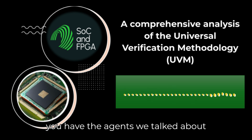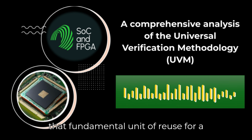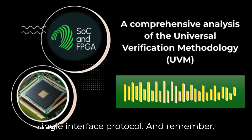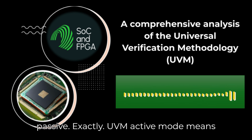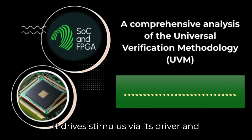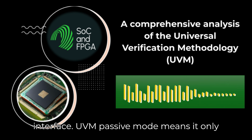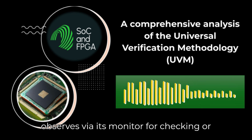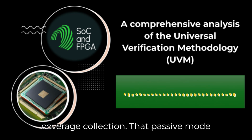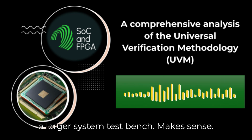And inside the environment, you have the agents we talked about earlier. Right. The UVM agent is that fundamental unit of reuse for a single interface protocol. And remember, it has those two modes. Active and passive. Exactly. UVM active mode means it drives stimulus via its driver and sequencer, and it also monitors the interface. UVM passive mode means it only observes via its monitor for checking or coverage collection. That passive mode is crucial when you reuse an agent inside a larger system test bench.